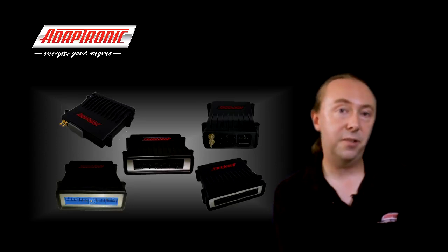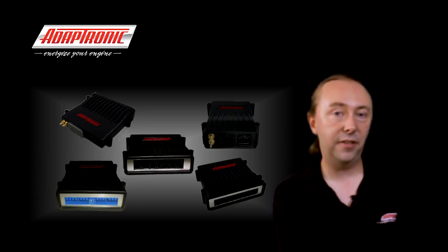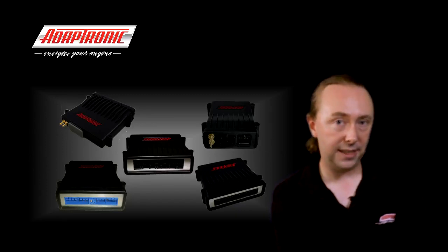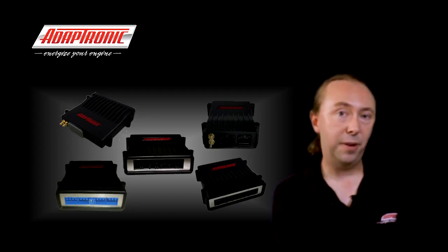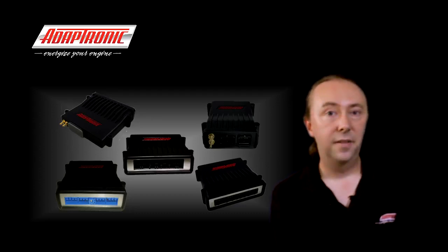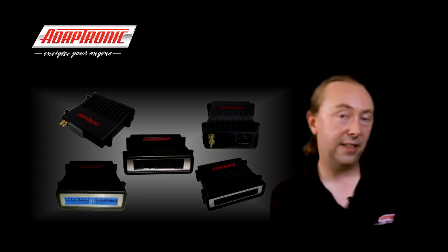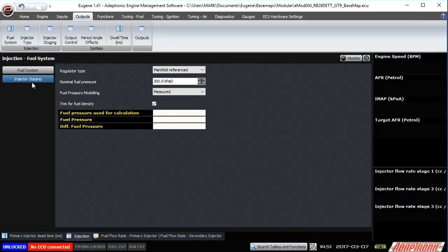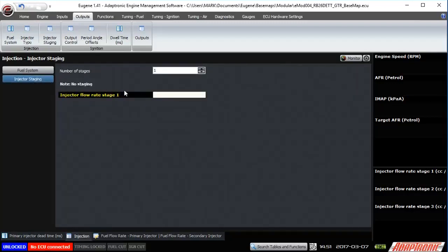For measuring fuel temperature, you can either use a discrete fuel temperature sensor like a coolant temperature sensor, or you can use the temperature output from an ethanol content sensor, since they output both the ethanol percentage and the temperature. If you prefer to model heat soak effects yourself, then you can turn this off and then compensate for this in the fuel modelling.